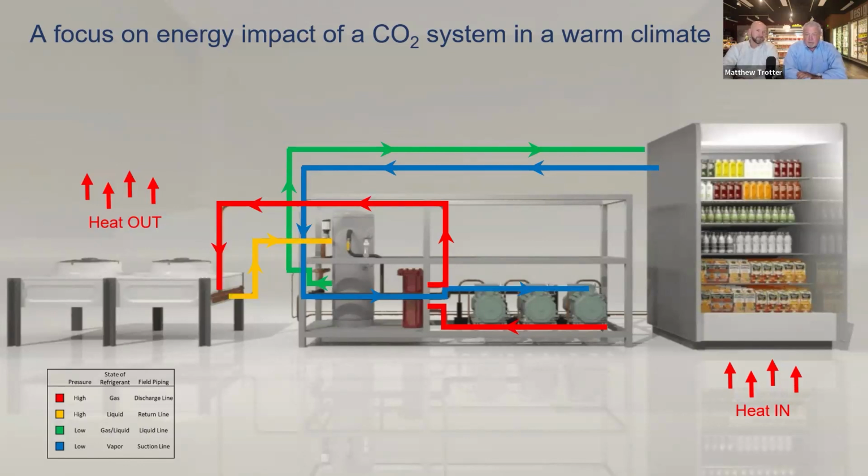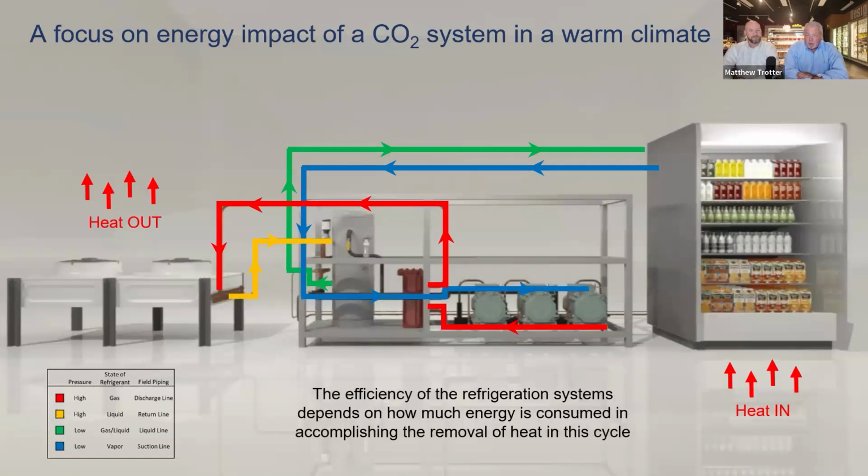Now, when we talk about efficiency in a refrigeration system, there are a lot of components that we look at across the industry of how we improve refrigeration efficiency. Looking at the display cases, electronic expansion valves, how do we do different things with the coil surfaces? How do we control superheat? Then when we come back to the compression system, what type of compressors are we using? What type of unloaders? How are we taking the efficiency of the compressors in mind with either digital, variable speed, or VFDs within the compression side?